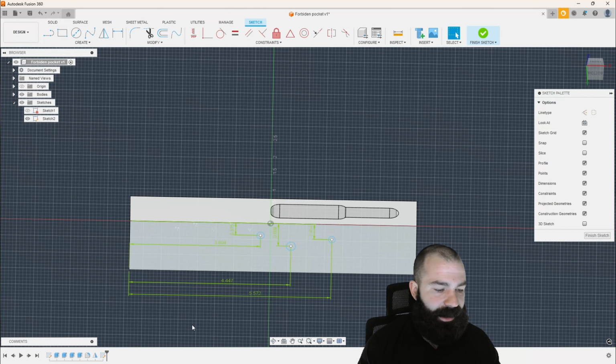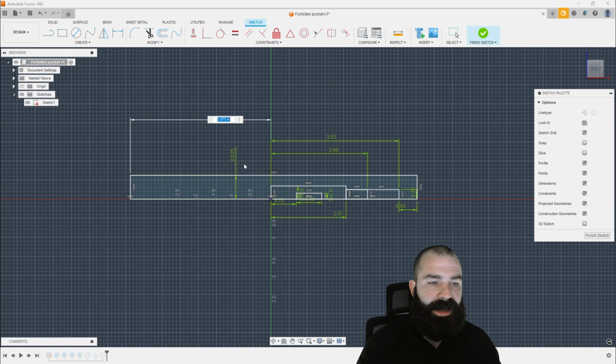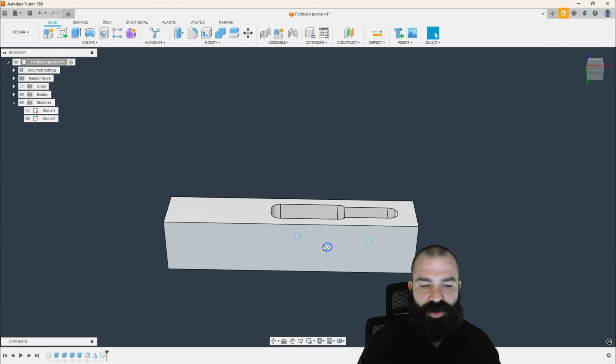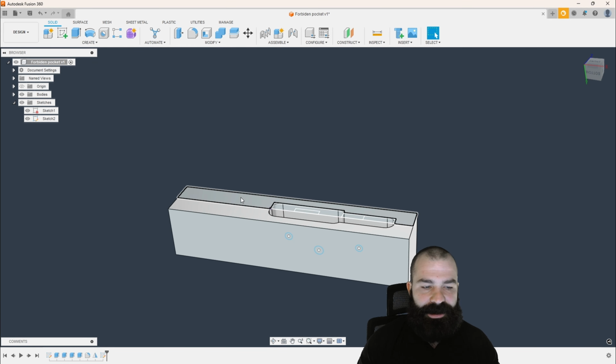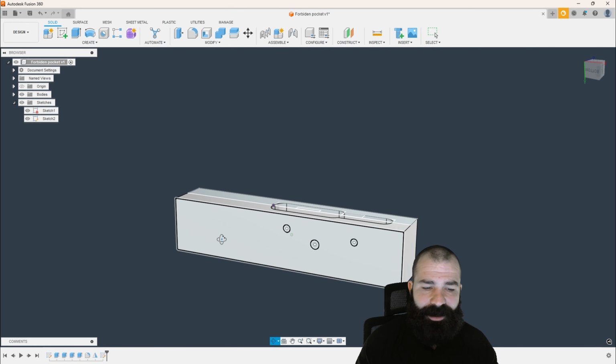I'm going to adjust that by saying finish sketch. I constrained everything off this edge, which is the key element. But if I go to my initial sketch, and let's just say this dimension was actually 2 something now instead, when I hit finish sketch, you're going to notice that those holes have all now moved, because this length of the actual cube changed in that first sketch. That actual distance changed, and we're constrained based on the origin. So that slid our actual reference edge down, constraining where all of our holes are. Again, you guys are going to want to check your dimensions and make sure that you have them all set.